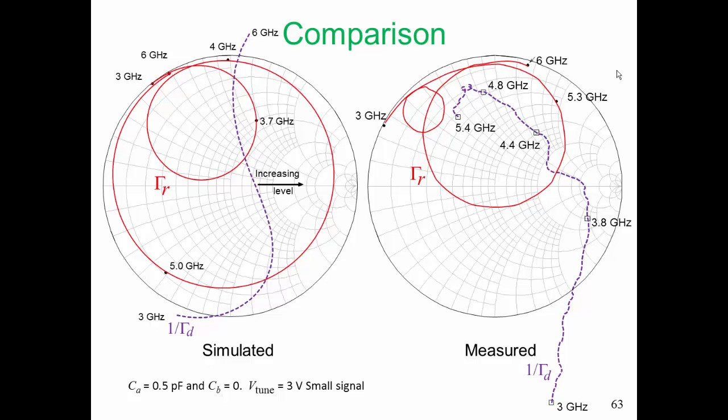On the measurement side, we are doing measurements of resonance circuits, and they're always very difficult things to do. For example, this crossover point that we simulated corresponds to a conductance of 0.4 Siemens or 2.5 ohms. When we make a connection during measurements, it is very difficult to have less than a half ohm resistance.